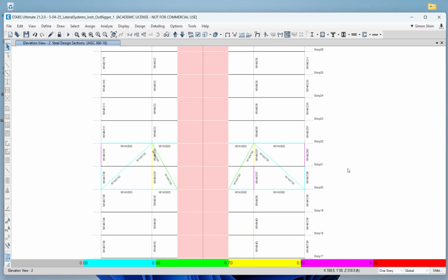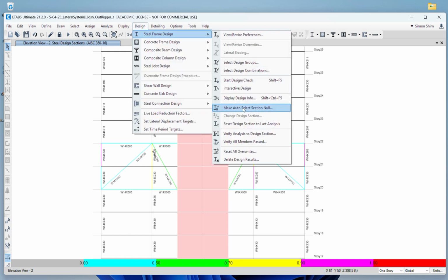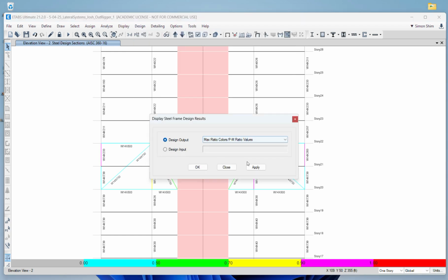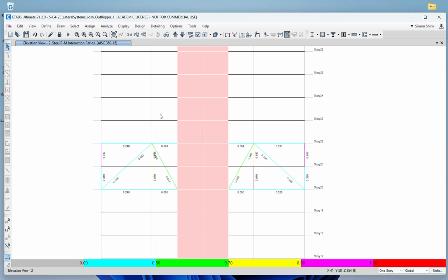Okay, so what you see, a pretty color, and go to design. Let's turn on the stress ratio. So what we did, two things, I think this is column size changes. First of all, initially the diagonal bracing was spanning from here to here, which means this diagonal hit the interior column, which actually generates bending moment.